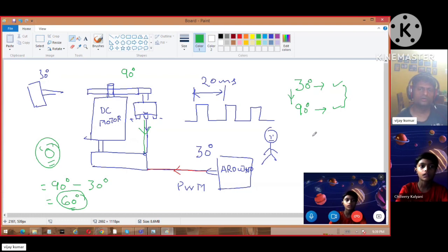Yeah, you're right. But since it's a learning phase, we'll start with one DOF, where we'll be controlling only one angle, one theta, and then after that we can add two servos and control theta 1 and theta 2, and then we can increase the motors, and the complexity will increase, to understand these variables again. So we'll start with 1 degree of freedom, and at the same time you will understand we will be using a servo motor for our maze solving project also.